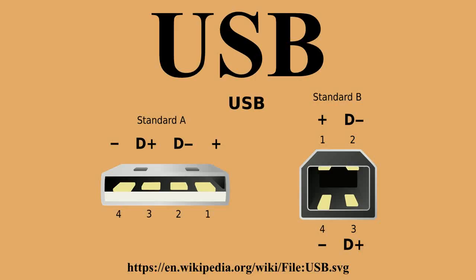Low power and high power devices remain operational with this standard, but devices using superspeed can take advantage of increased available current of between 150 mA and 900 mA respectively. Additionally, there is a battery charging specification, which increases the power handling capability to 1.5 A but does not allow concurrent data transmission. The battery charging specification requires that the physical ports themselves be capable of handling 5 A of current but limits the maximum current drawn to 1.5 A.